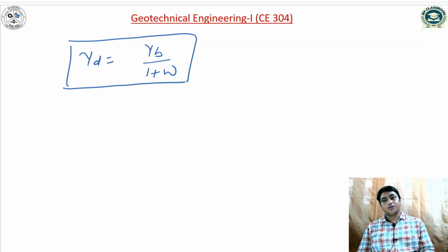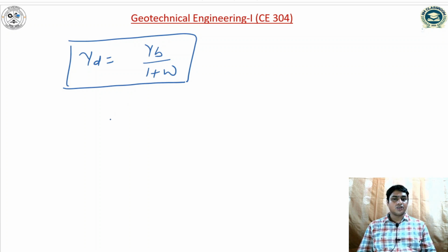So this is an in-situ method to compute the density of the soil. What I said, firstly take the empty cylindrical core cutter and measure the internal diameter and height.